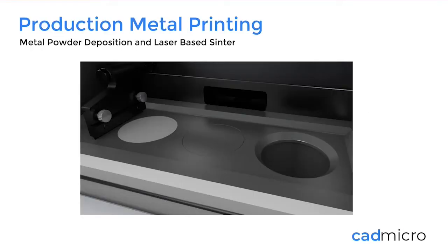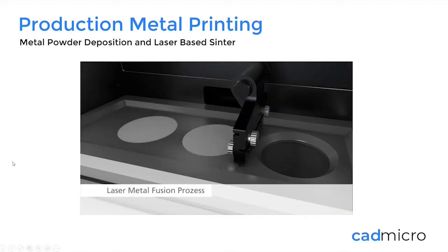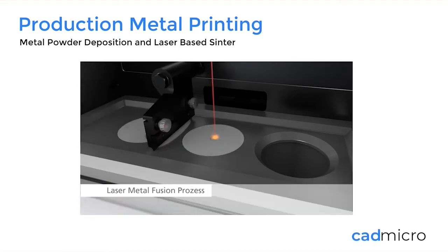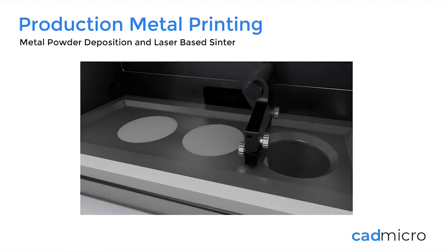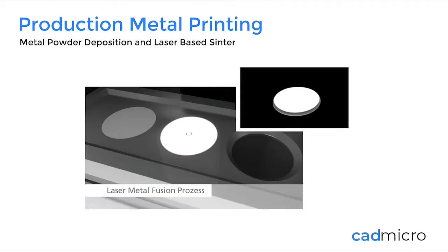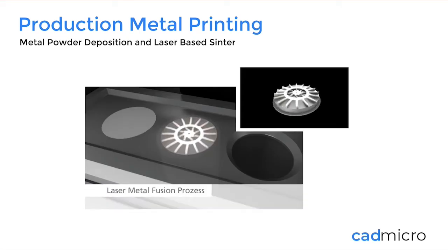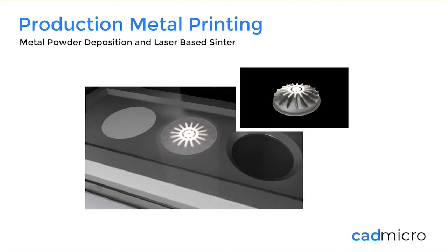So this is a very quick video, briefly demonstrating the fundamentals of powder-based metal 3D printing. A fine line layer of powder is deposited on the build plate. It is then fused through laser thermal energy with extremely high resolution over an iterative process, layer by layer. It builds it up within the build chamber surrounded by powder, and following the manufacturing of the part, the powder is then removed. It literally just falls away with no post-processing. You get your finished metal part.